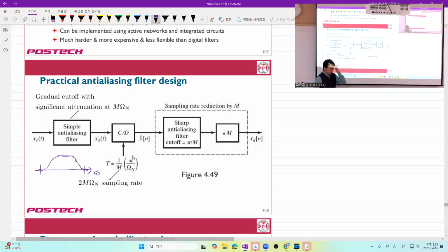So usually we think, okay, let's do ideal sampling at a low rate, for example 44.1 kilohertz sampling with a very sharp anti-aliasing filter. That's not happening. They have a little bit slowly rolling-off filter, but with twice or 4 times higher frequency, high quality sampling.